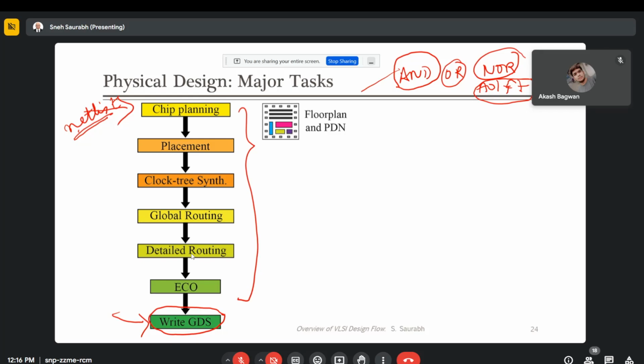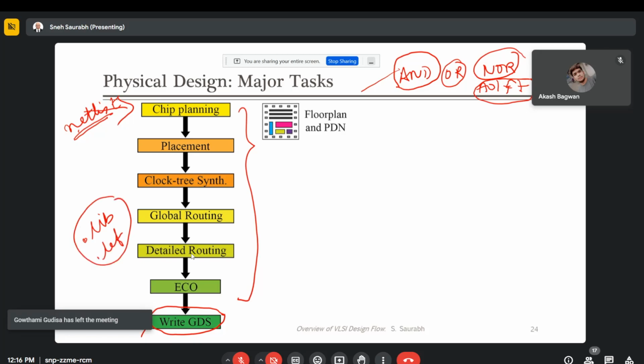Once that AND gate is made, the information of that AND gate is extracted from the layout and put in the .lib file, .lef file, and other formats, which have some abstract information of these cells and which will be used subsequently in the design flow.